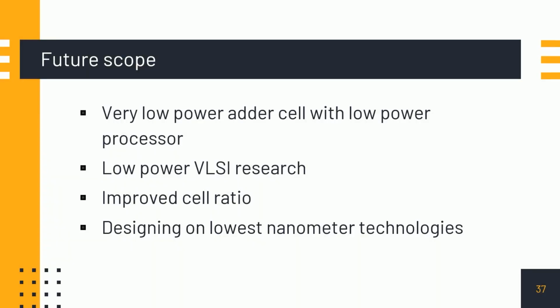Low power VLSI research opens new techniques for reducing power in the field of processing and adders. As future work, we can extend the work by applying different architectures of full adder using different gates. We can improve the performance of each of these designed 1-bit full adder blocks by varying their cell ratio or by adding passive elements like resistors or capacitors.